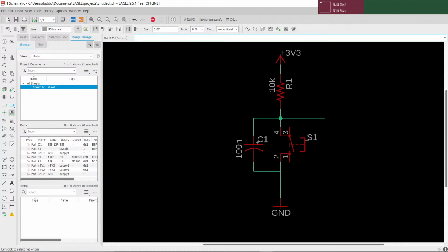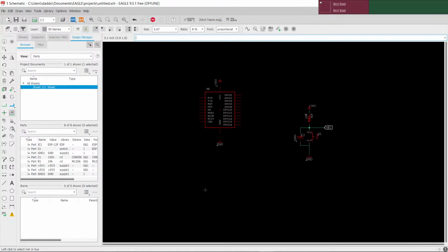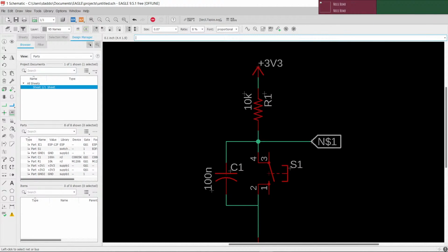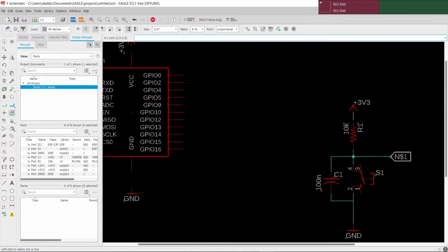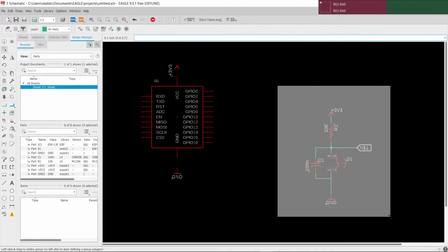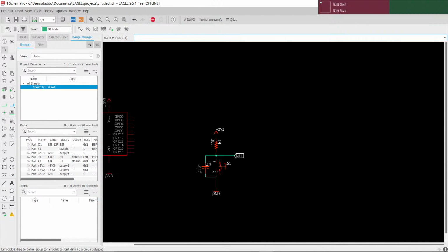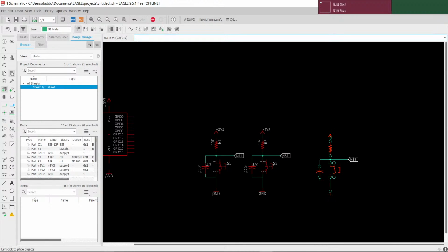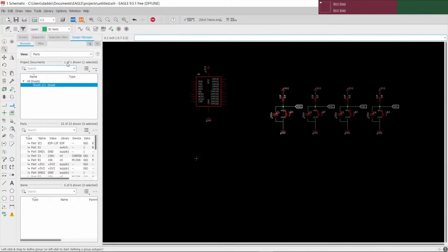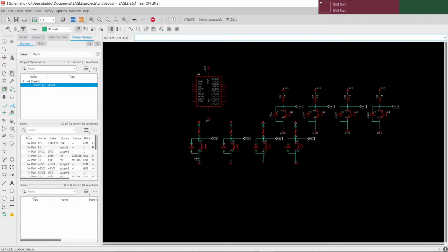connecting, I will be using a label to connect the actual pins, the actual net here to the GPIOs here, because it's much better to not connect stuff with wires like these, for example. Yeah, using labels is much tidier. So now I can Control C and I can Control V. 1, 2, 3, 4. So, and now I can do this, and